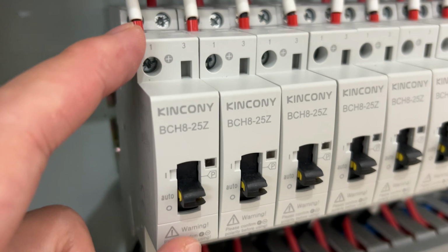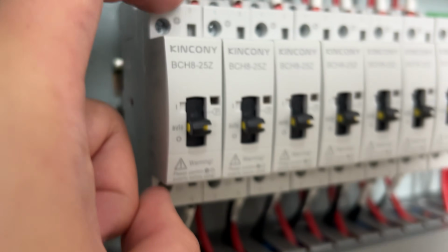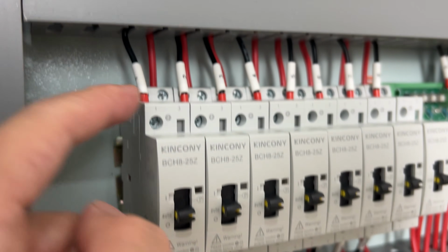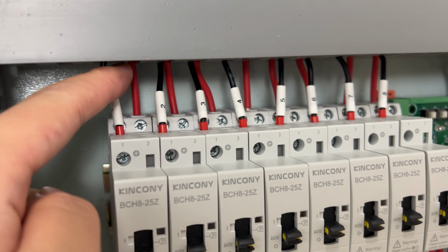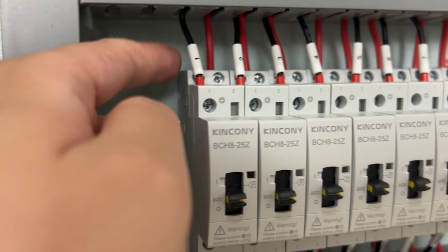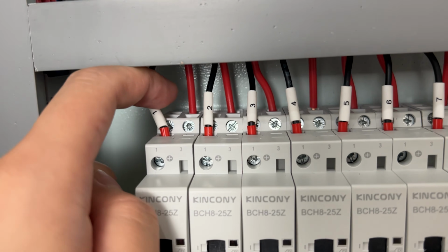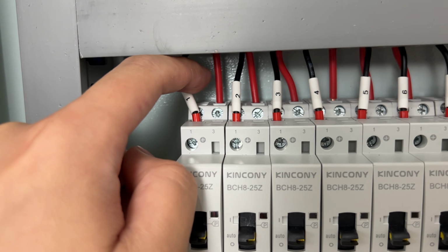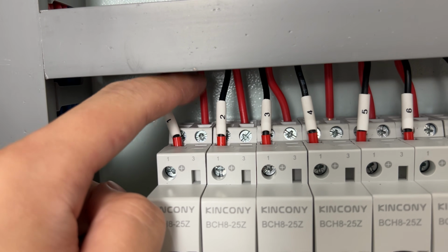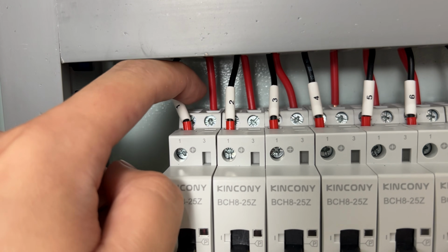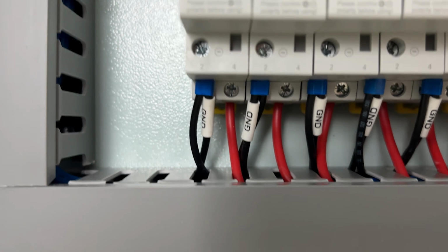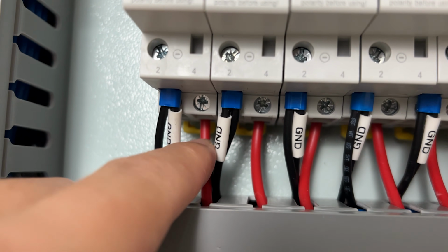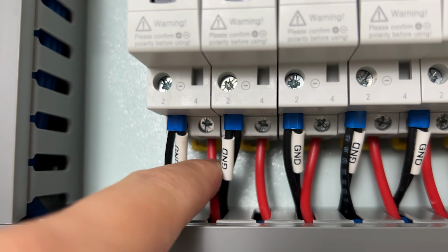Okay, and this contactor. And this contactor, you can see here that is the coil voltage. And this has two channel outputs. This is in, this is in, and another channel I have not used. If you want to use it, this is the live line in, and this is the neutral line in. And at the bottom, you can see that is the live line output.